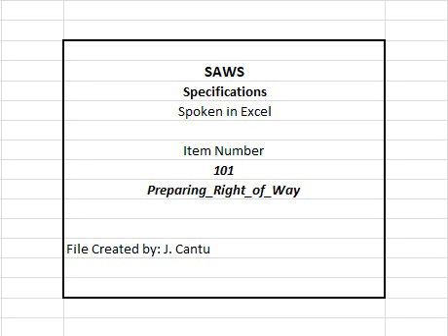5. Unless otherwise indicated in the contract documents, all underground obstructions shall be removed to the following depths. A. In areas to receive embankment, 2 feet below natural finished grade. B. In areas to be excavated, 2 feet below the lowest elevation of the excavation. C. All other areas, 2 feet below finished grade.